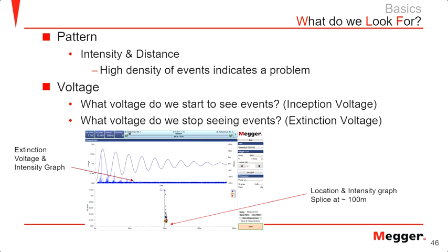That means if you're bringing your voltage down to 1.2 times your operating voltage and your partial discharge doesn't appear anymore, then it's obviously a good thing because your extinction voltage is higher than your operating voltage, and the partial discharge stops at that 1.2 times, and obviously it is much more beneficial to do that.